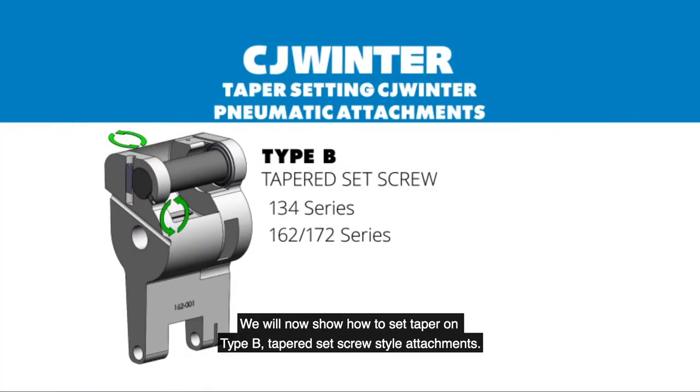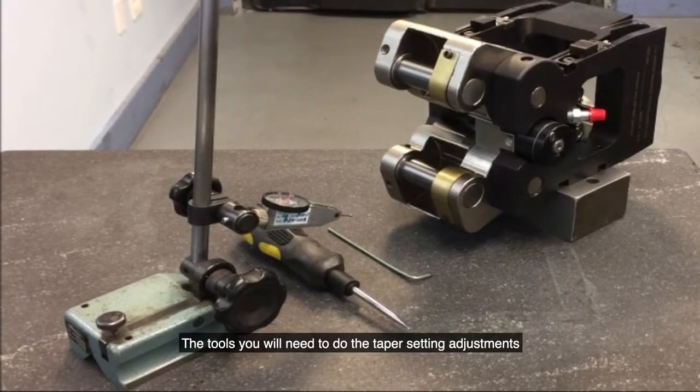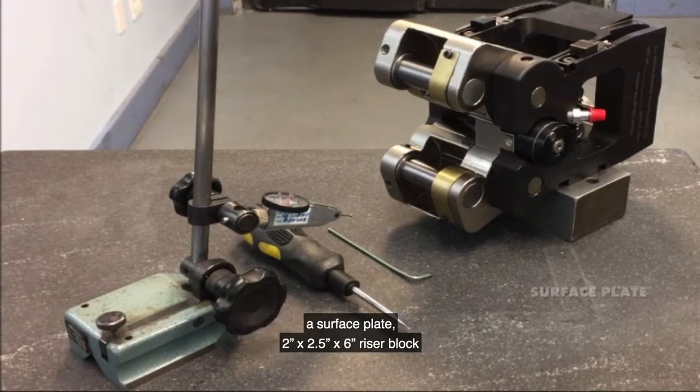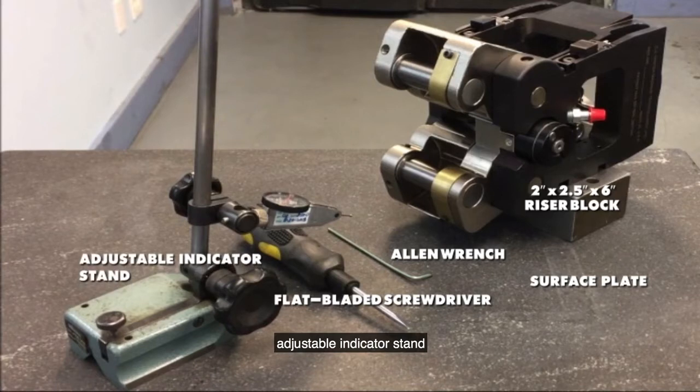We will now show how to set taper on Type B taper set screw style attachments. The tools you will need to do the taper setting adjustments for the pneumatic attachments for Type B, or 134 series, 162, 172 series, are a surface plate, 2 by 2.5 by 6 riser block, Allen wrench, flat bladed screwdriver, adjustable indicator stand, and a 1/10 resolution indicator.